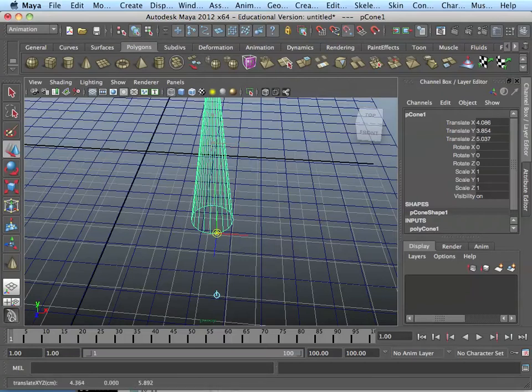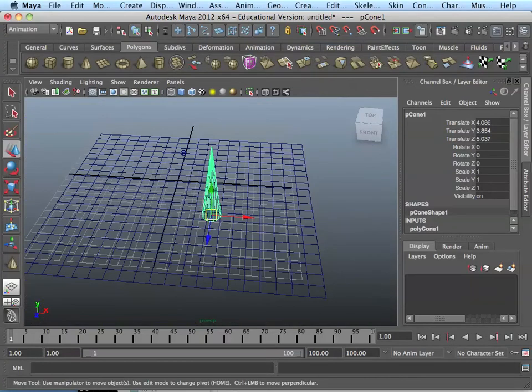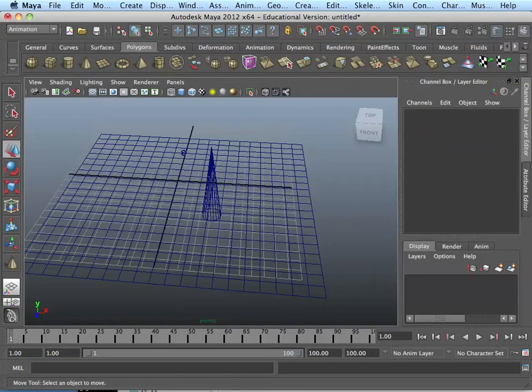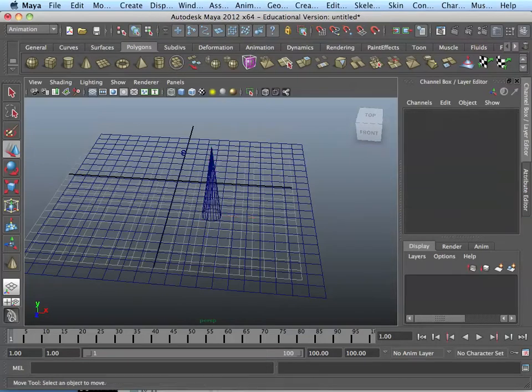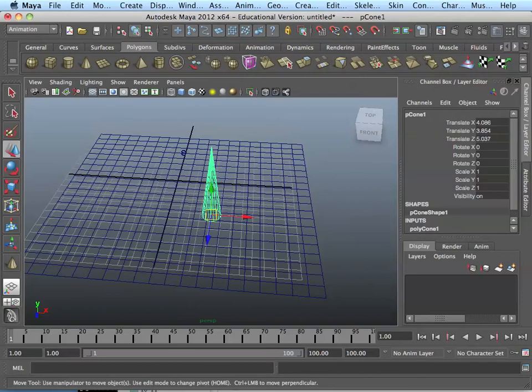And now you can see I'm moving the pivot point rather than the object. There are ways around it, but I'm just going to eyeball it right now, because that's close enough. So, can you assign multiple pivot points to an object? No, you cannot. The way you can fake having multiple pivot points is you group it to itself, right? Normally you think a group needs multiple things.